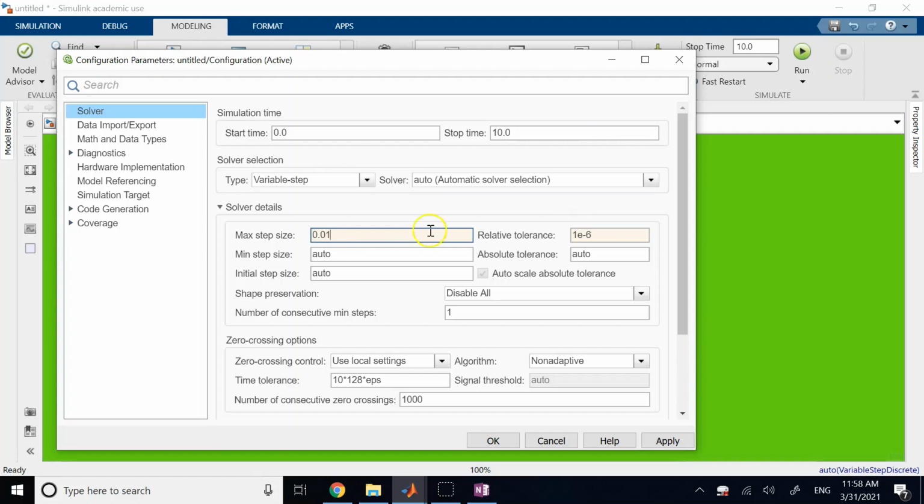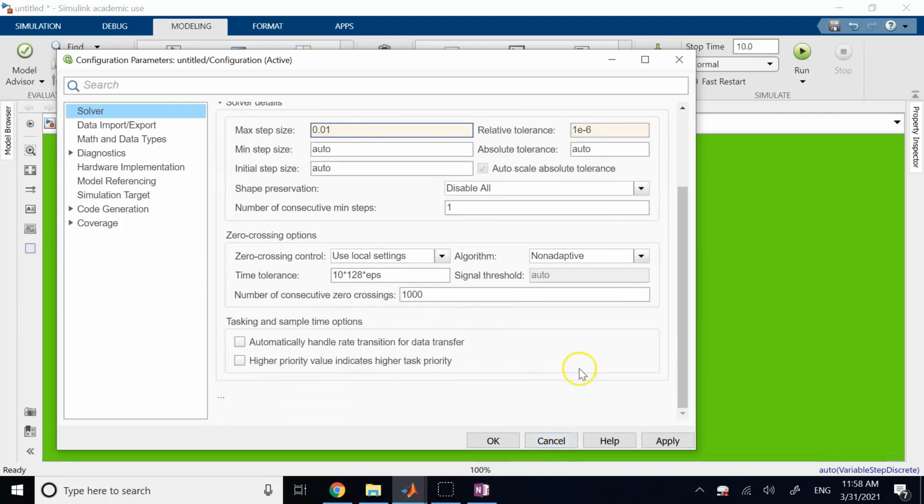And this is really going to help you for the third problem of the second bonus project. Okay, that kinetic energy problem and the car hitting into barriers. If you really want to see the velocity of the car converge to 0 when s goes to 18 feet, you need to bring these numbers down to see that happening. Okay, so this tolerance, zero crossing, and other stuff are important things.